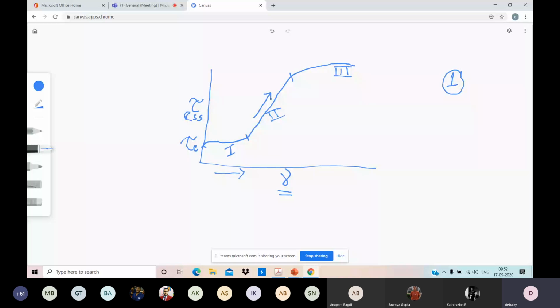And eventually, when the number is very high, so much stress will be generated that the stress will be very high to cause further deformation. So at that point, what will happen? Some of the dislocations will move into another plane or recover.